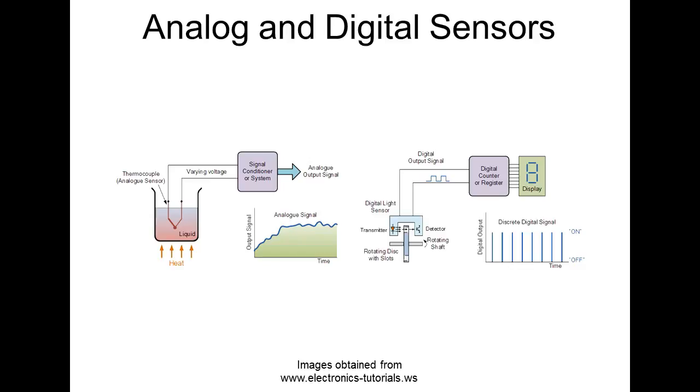So your thermostat has both of these. And so what we're doing is taking an analog sensor and bringing it into a digital world. If I'm going to bring an analog sensor into a computer that is digital, we're going to go through a device called an A to D, an analog to digital converter. A lot of your sensors have that A to D converter built in.